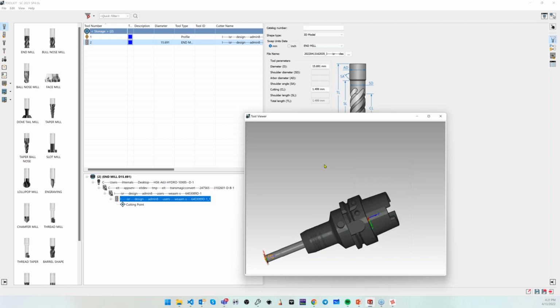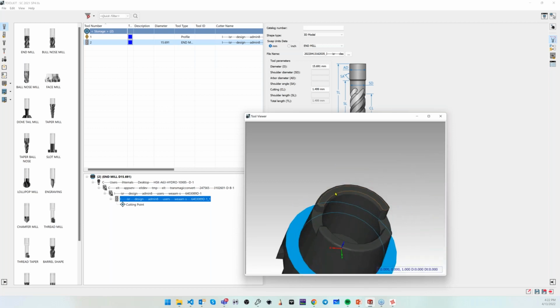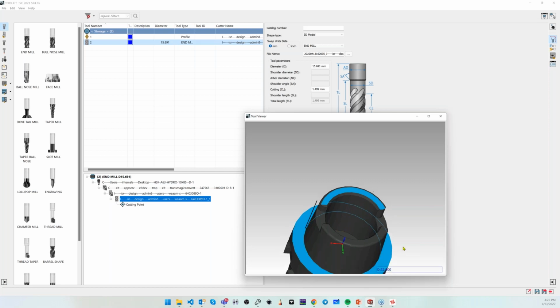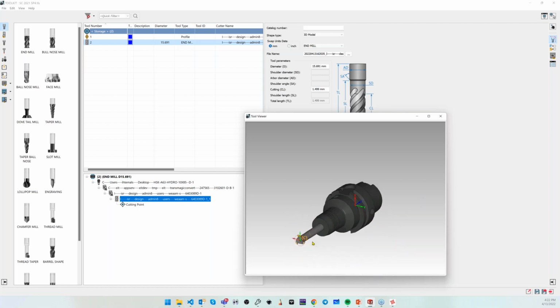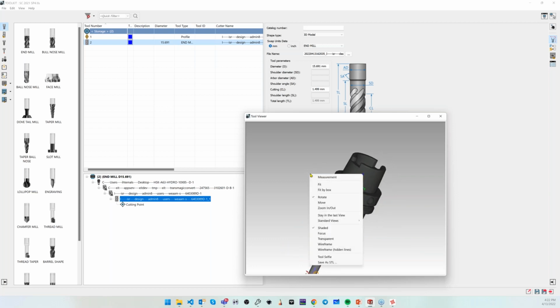It is a measurement. Once you activate the measurement, the faces on the STL file, on the 3D model, become selectable. If you want to measure the distance, you just click on two faces while holding the Control button, and you get the measuring dimensions, 32 millimeters, for example, here. You can measure between 2 points, between 2 faces, and any other measurement you need. So it's a very powerful tool. If you don't like this strange behavior of the selected faces, you can just disable this measurement and it will behave as we used to.